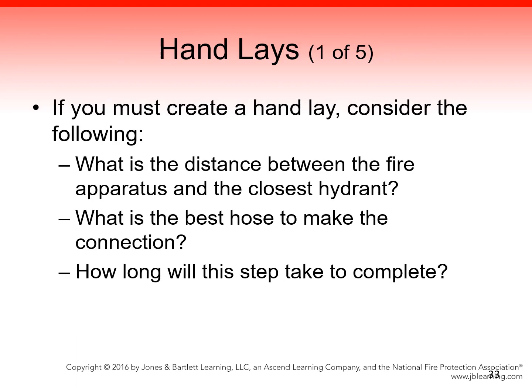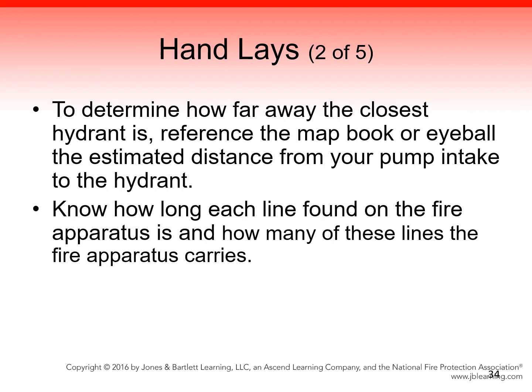Hand lays. If you find yourself having to create a hand lay to a hydrant, several considerations must be taken into account. What is the distance between the fire apparatus and the closest hydrant? What is the best hydrant to make the connection? How long will this step take to complete? To determine how far away the closest hydrant is, either reference the map book in your fire apparatus or simply eyeball the estimated distance from your pump intake to the hydrant.